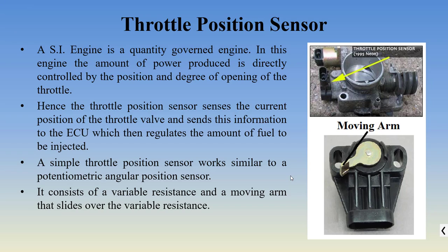In that case, what should the engine do? Engine should increase the amount of fuel that is being injected. But if you are only cruising, that is, you have not pressed the accelerator pedal directly to the bottom, you have pressed only a little bit, then the amount of fuel injected should be less. That is why we need a throttle position sensor.